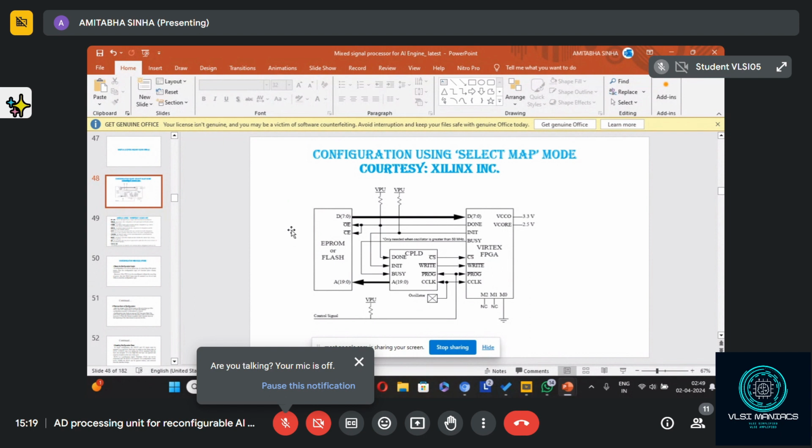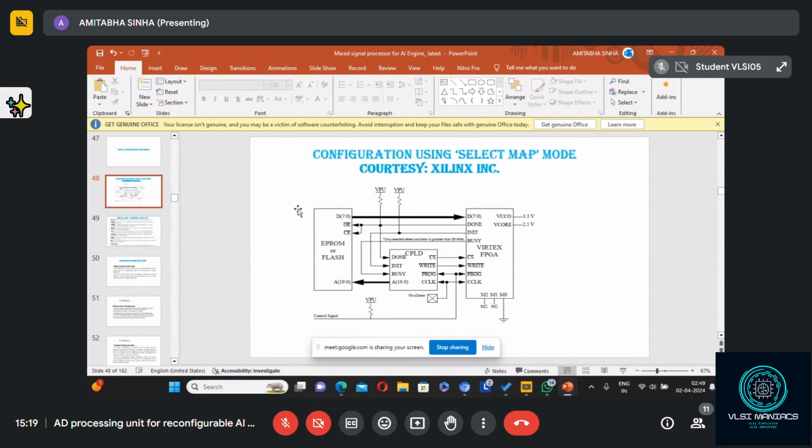Now, once these bit streams are downloaded, how do we identify which bit stream is for what? The identification mark is their starting address and how many bytes are to be downloaded. For example, let's say a FIR filter has been stored from location 0 to location n-1.